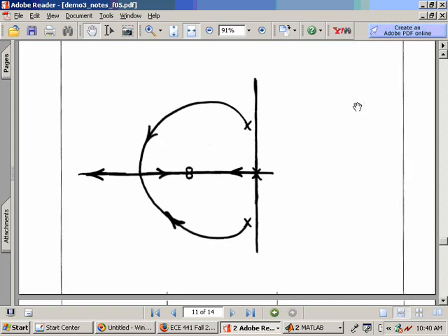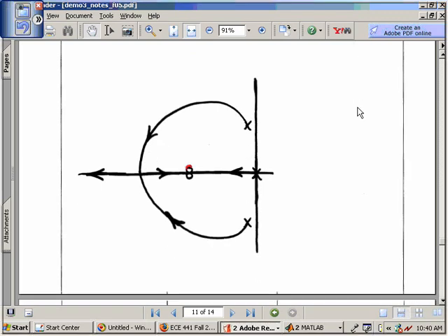A third possibility would actually maybe be the easiest to design with, and that is to locate both of our PID zeros at the same location. In this particular demonstration, we're going to locate those both at -20. One of the poles, which is due to the integrator term, is going to go to one of those zeros. These two are going to approach the real axis and re-enter.